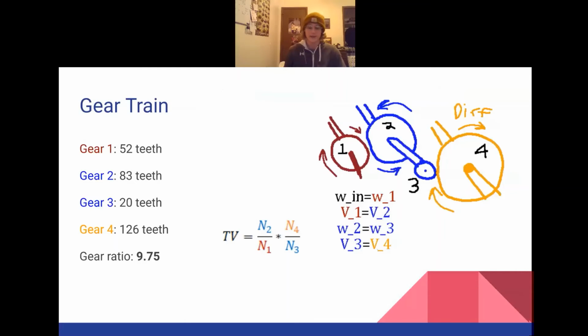For the gear train, in order to achieve a similar gear ratio to that of our reference vehicle, the Tesla Model S75, of 9.73, the number of teeth per gear is as follows, and a gear ratio of 9.75 to 1 was found for this project. The diameters of the gears for our gear train model were calculated based on these gear teeth numbers, as well as the tooth size and circular pitch, though force studies were not conducted on the gear teeth for this project.